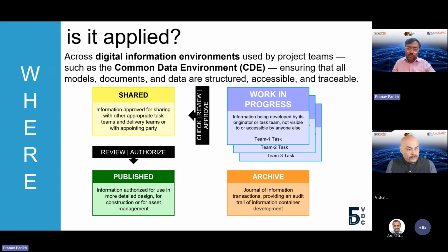We're not going to start looking at data in WIP, right? We are only going to go to shared to do the collaboration and coordination. We're not going to go to the published folder and start commenting, because those are technically approved files, right? So again, there are certain standards. The BIM managers and the other documents will take care of it, but that's the logic of the WIP, shared, published, archive concept of ISO 19650.